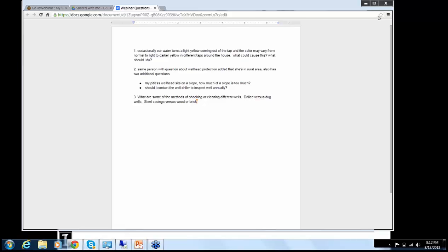We believe what they recommend and all the detail they provide not only show you how to chlorinate your well, but also talk about all the other issues that might go along with that, like making sure your pump's off and some of the safety issues with electricity that go along with that. And so, there's formulas for how much chlorine to use depending on how much water's in your well and how big the diameter of your well is and some of those things.